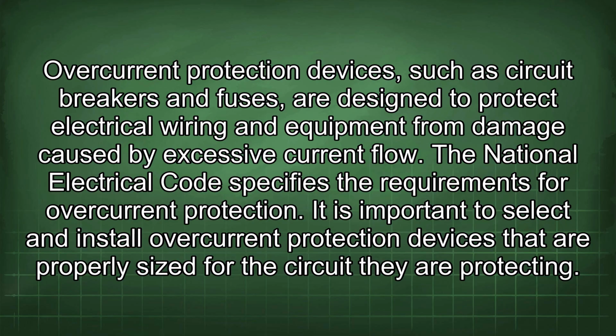Overcurrent protection devices, such as circuit breakers and fuses, are designed to protect electrical wiring and equipment from damage caused by excessive current flow. The National Electrical Code specifies the requirements for overcurrent protection. It is important to select and install overcurrent protection devices that are properly sized for the circuit they are protecting.